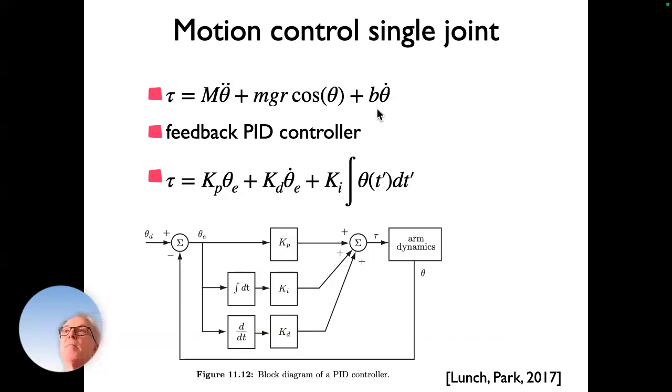This would be damping. And remember, we're thinking in robotics that the actuator gets a torque signal as a command. So we've taken care of the motor, so whatever we give to the motor electrically actually amounts to a torque. We just want to determine what kind of torque we should insert into that system.